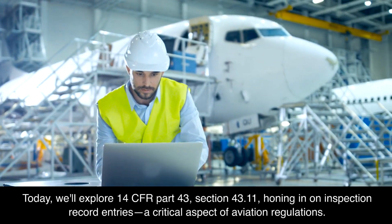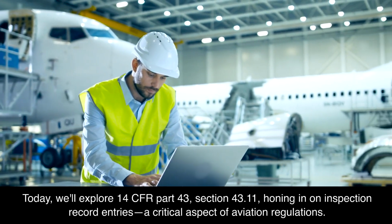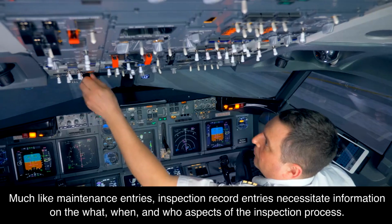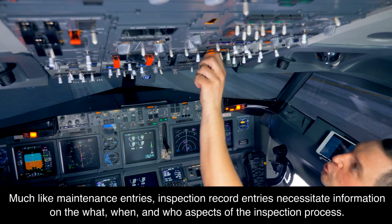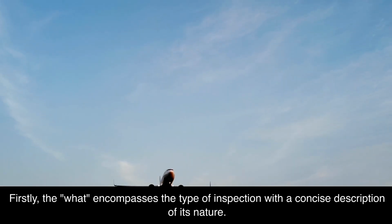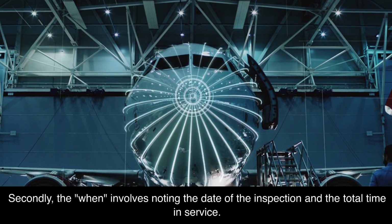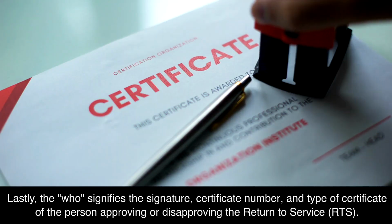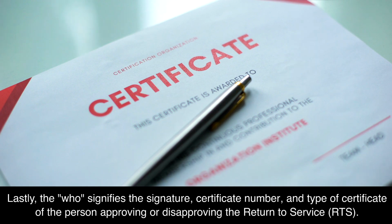Today, we'll explore 14 CFR Part 43, Section 43.11, honing in on inspection record entries, a critical aspect of aviation regulations. Much like maintenance entries, inspection record entries necessitate information on the what, when, and who aspects of the inspection process. Firstly, the what encompasses the type of inspection with a concise description of its nature. Secondly, the when involves noting the date of the inspection and the total time in service. Lastly, the who signifies the signature, certificate number, and type of certificate of the person approving or disapproving the return to service, RTS.